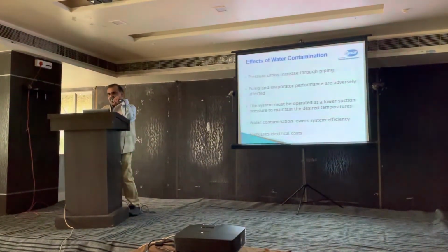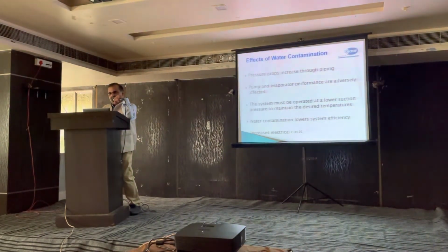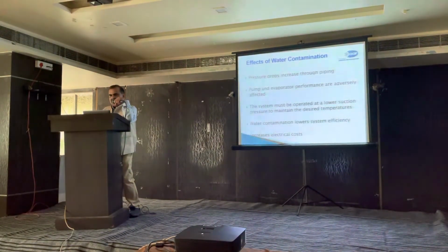Pump performance will be affected, and as I said, for suction pressure, you need to operate at a lower suction pressure, which means you need more power. So overall efficiency will go down and electrical energy cost will increase.